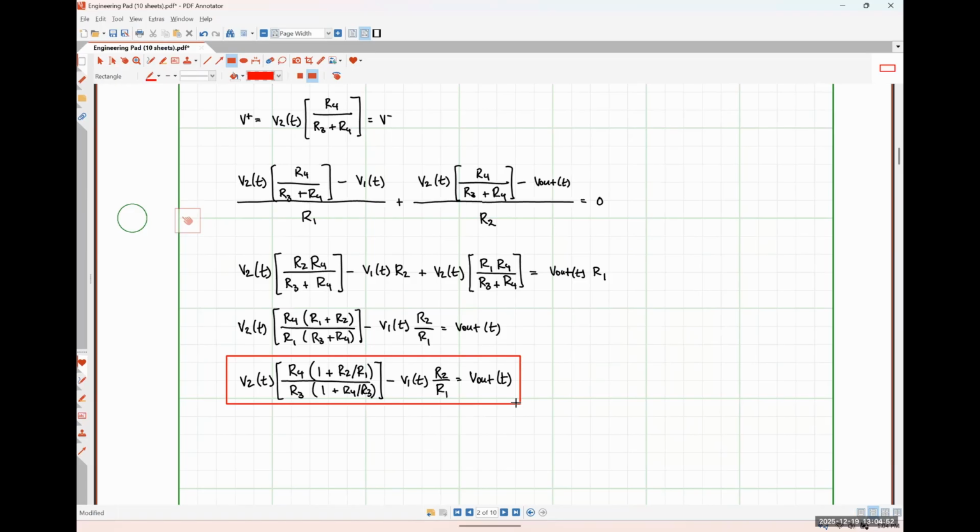Still just a different thing, but it's just affected by different resistor values. Exactly right. And if we chose R4 over R3 having the same ratio of R2 over R1, we'd get literally just R2 over R1, a differencing amplifier relationship. So the instrumentation amplifier doesn't have to have the unity gain amplifiers attached to it, or is that like?